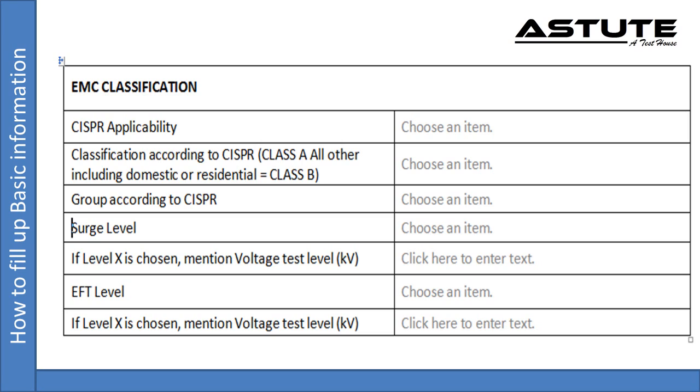Level 4. Severe industrial environment. The installation is characterized by the following attributes. No suppression of EFTB in the power supply and control and power circuits which are switched by relays and contactors. No separation of the industrial circuits from other circuits associated with environments of higher severity levels. No separation between power supply, control, signal, and communication cables.